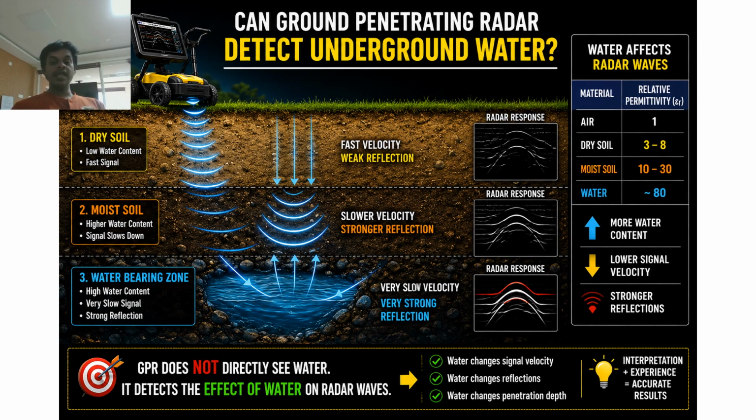In fact, many professionals combine GPR and resistivity surveys together. GPR will provide high resolution shallow information. Resistivity will provide deeper groundwater information. Together, they can become a powerful investigation tool for groundwater studies.